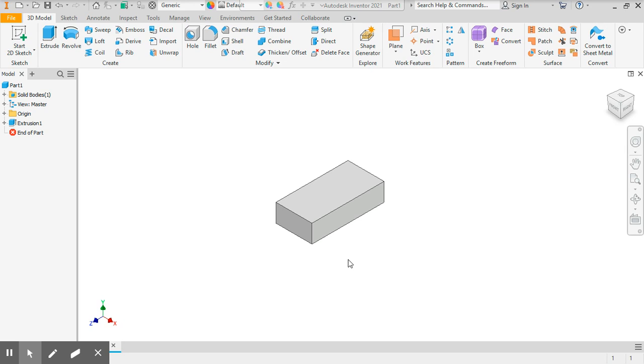Now a couple more tools. I guess I thought I was done, but there's 3 more tools I want you to see in this tutorial before we end. And they are mouse movements. So again, tech tips, you'll want to write these down. The first one that we use a lot in Inventor is called the pan tool, P-A-N. You work with this by holding your shift button down on your keyboard, holding the middle mouse button down, and then you can drag. It's not going to work on my computer today.